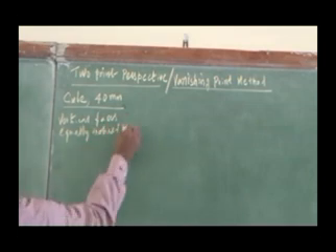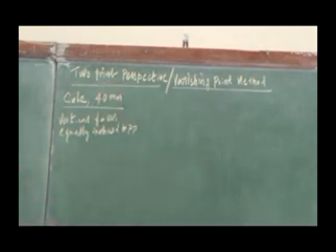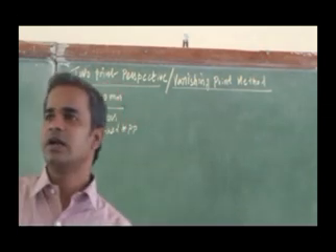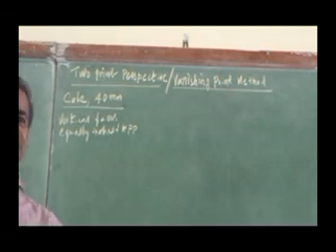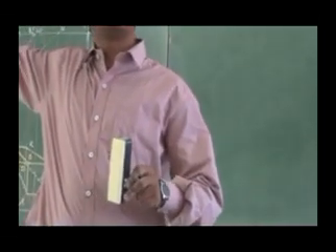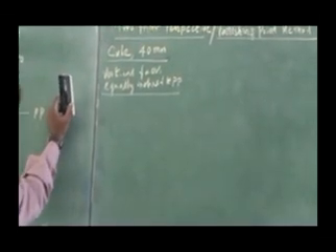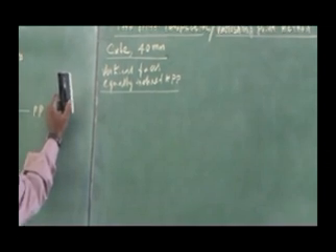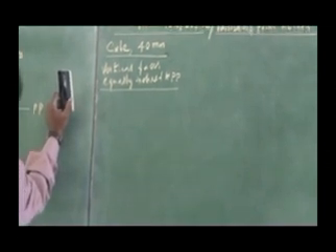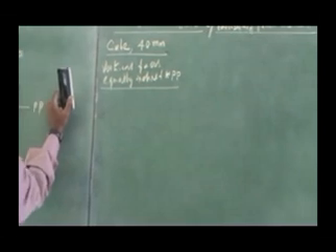to PP, the picture plane. So far we have seen the solid's face parallel to the picture plane. Very well, I can go for a single point perspective, that is the vanishing point visual ray method. Now the vertical face is equally inclined to the picture plane. So even though here also I can go for single point perspective, the same previous procedure I can follow, okay, I can get it.